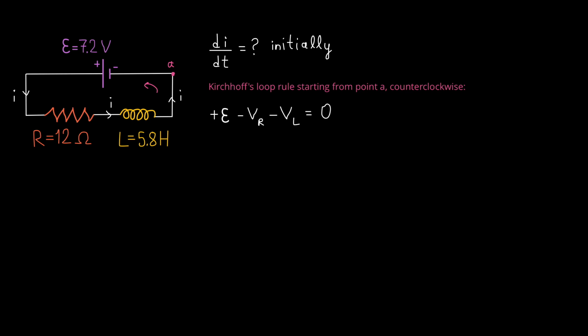Why is there a decrease in potential? Now, if you think about the direction of the current in the circuit, it's counterclockwise. So for the inductor, the current goes from left to right and it's growing. The inductor will try to resist that change. If we had a battery instead of the inductor to resist the increase in current, the left-hand side terminal of the battery would have to be positive and the right-hand side terminal would have to be negative so that the battery can create a current in the opposite direction. And the inductor's terminals will follow the same order.